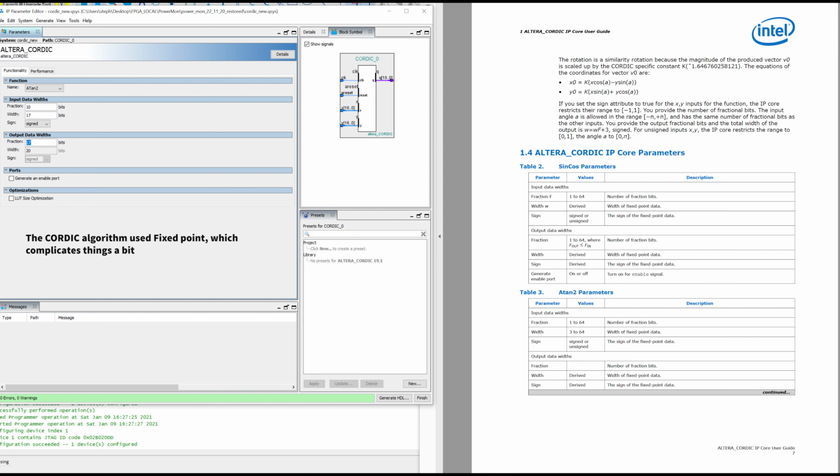So bits 18, 19, and 20 have to be enough bits to encode 0 to 3, which it is. And then the fractional bits will represent the fractional part of this number. That's the bit where we want the resolution. So that's why we dedicate more bits to the fractional part of it.